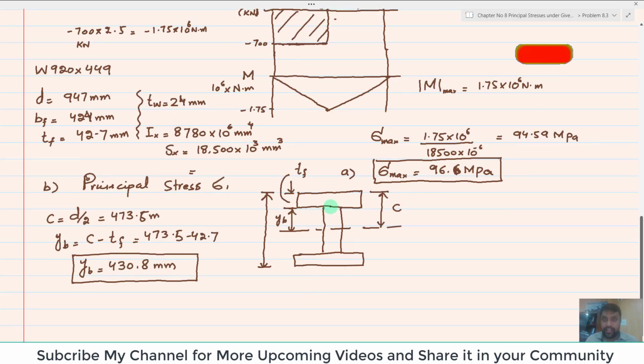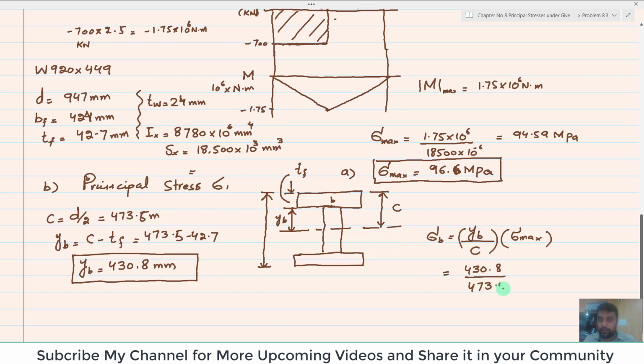Now for finding the stress at this junction, let this be point B, and we are interested to find out the normal stress at this junction, which is sigma B. So this sigma B will be equal to YB over C into sigma max. Clear? So this YB is 430.8 divided by C, which is 473.5, into 96.6 megapascal.